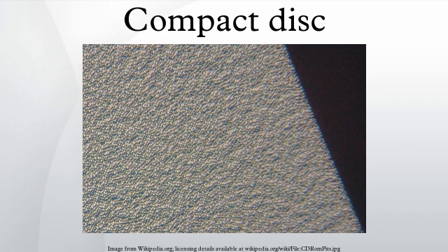Vinyl disc. Vinyl disc is the hybrid of a standard audio CD and the vinyl record. The vinyl layer on the disc's label side can hold approximately 3 minutes of music. Manufacture. Replicated CDs are mass-produced initially using a hydraulic press. Small granules of heated raw polycarbonate plastic are fed into the press. A screw forces the liquefied plastic into the mold cavity. The mold closes with a metal stamper in contact with the disc surface. The plastic is allowed to cool and harden.